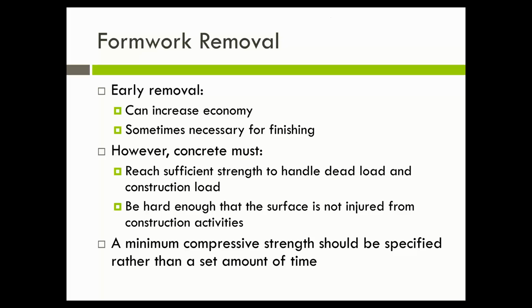3 weeks is a long time, and so often we design our concrete structure or other concrete mixtures, and the strength of concrete that we're putting in them is dependent not on what the specified strength is, but on an earlier age strength. For example, I want 4,000 psi at 28 days, but I want to remove my forms at 3 days, and I need 3,000 psi to do that. The 4,000 psi at 28 days, which is the contractual obligation, doesn't matter anymore because you will well exceed that so long as you are meeting the 3,000 psi at 3-day requirement.